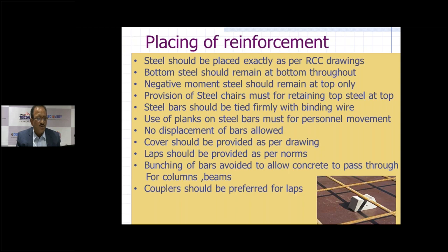So what kind of precautions should we take? Number one, steel reinforcement should be placed exactly as per the RCC drawings. Structural consultants provide us the RCC drawing, the steel reinforcement placement drawing. So the site engineers have to be extra cautious to see that the steel is placed exactly as per the RCC drawing.